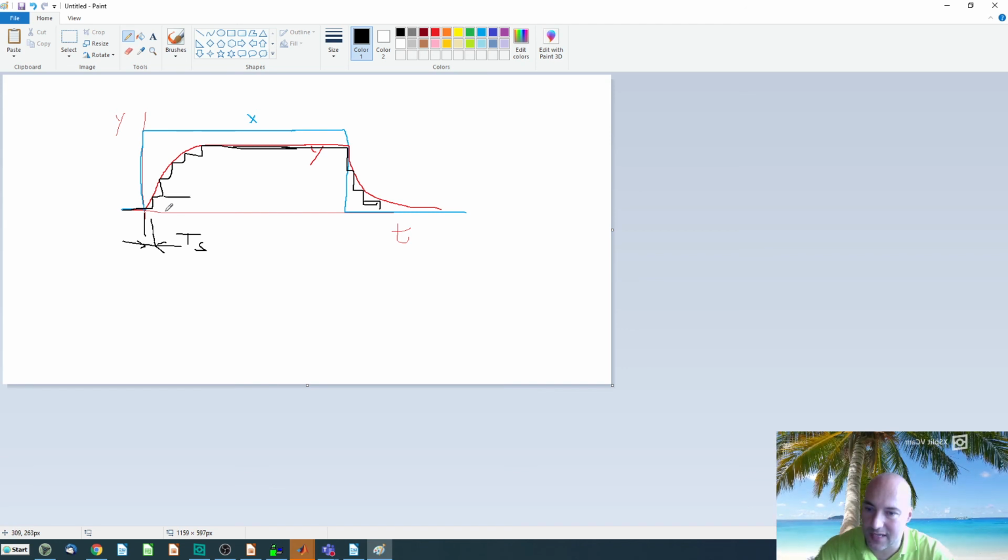And this will come from the AD converter, or from the granularity of your device. In any case, you would see this in the real world on the oscilloscope. So this will come from the resolution of the numbers that you will have in the Nucleo board.